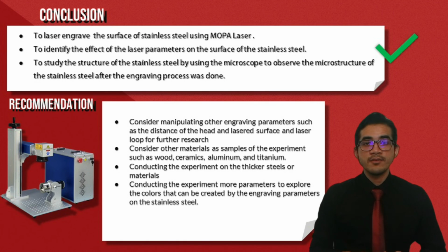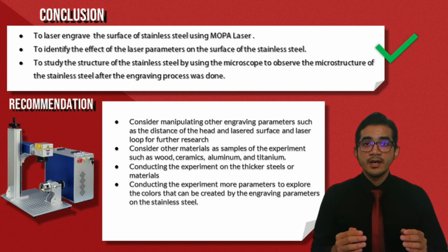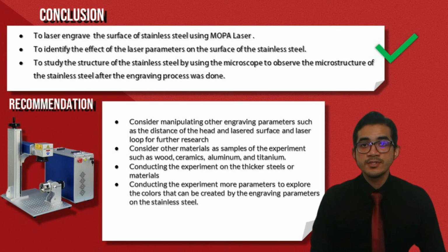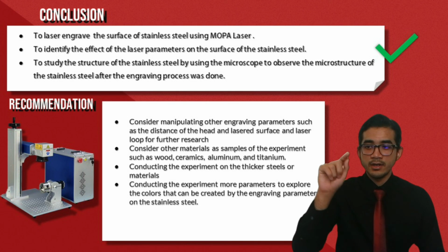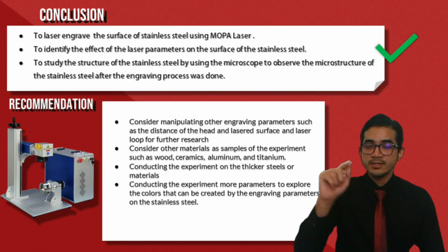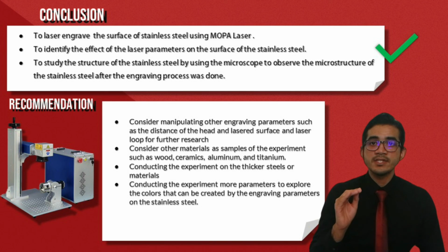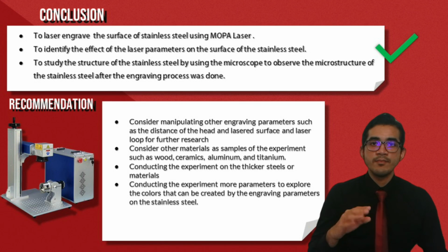And I can conclude that for experiment one, when the speed is higher, the value of the surface roughness is decreasing. When the speed is slow, it gives time to melt the surface of the squares, and if the speed is high, the burning time or lasering time is short, so the melting process is barely done on the surface.